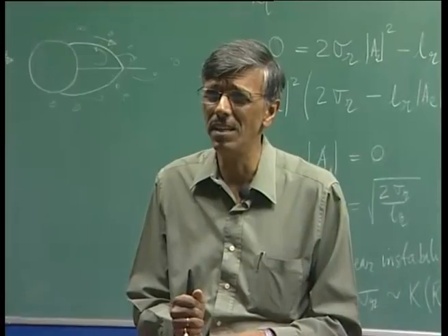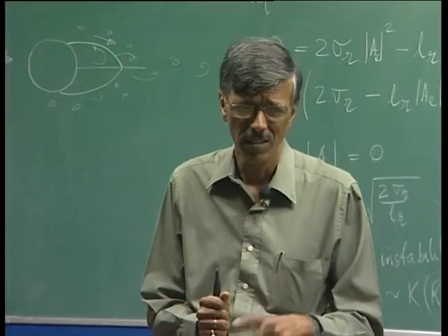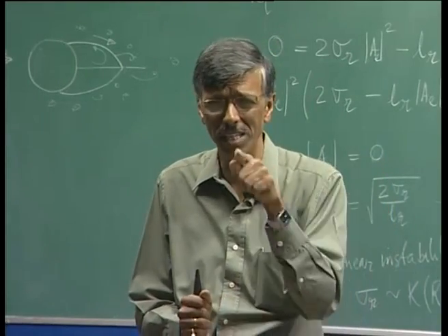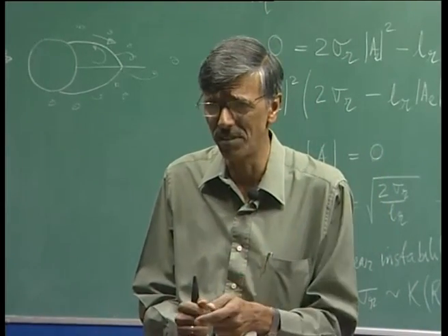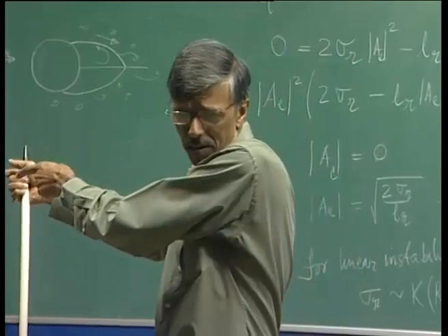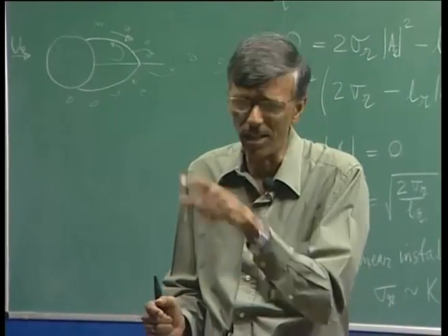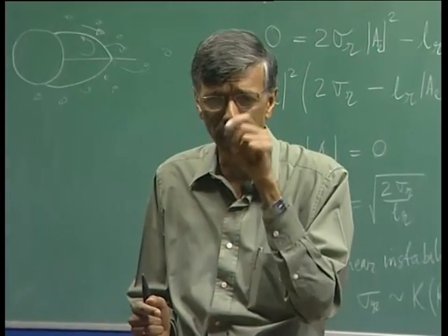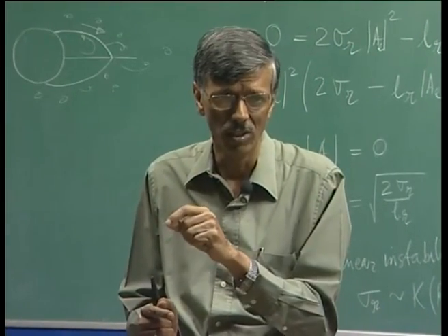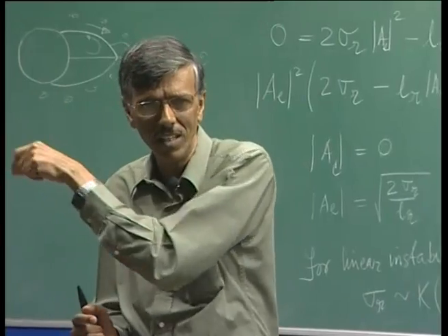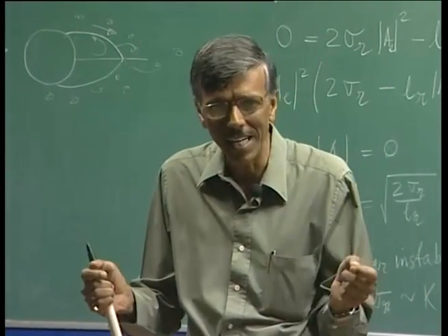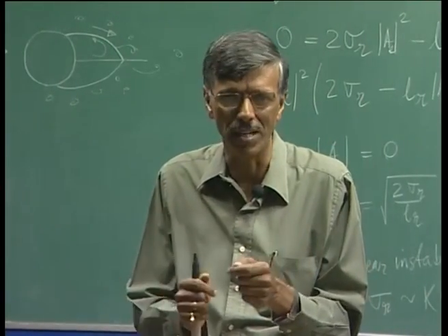So, basically to understand this nonlinear action by putting in a probe and measuring is rather difficult, but if I put it far downstream, because Strykowski and Sreenivasan mapped the region where you have to put this control cylinder, if I put it beyond that region, then I can study the wake.